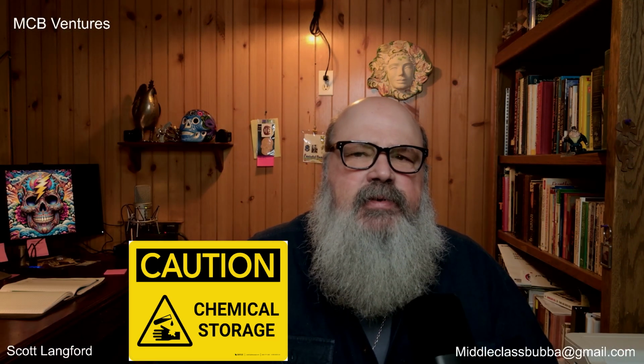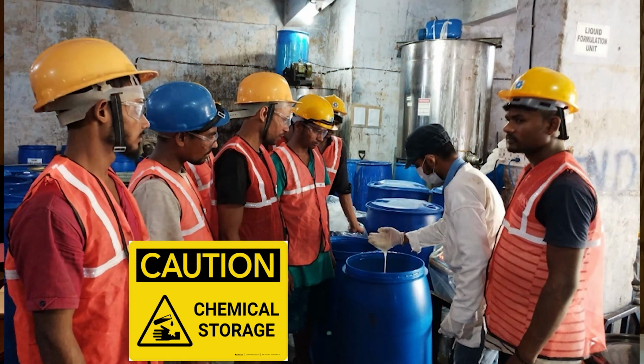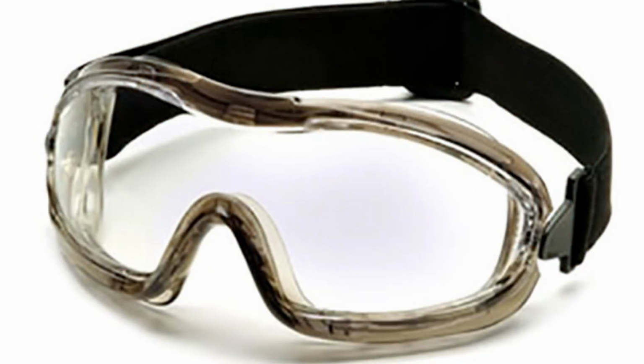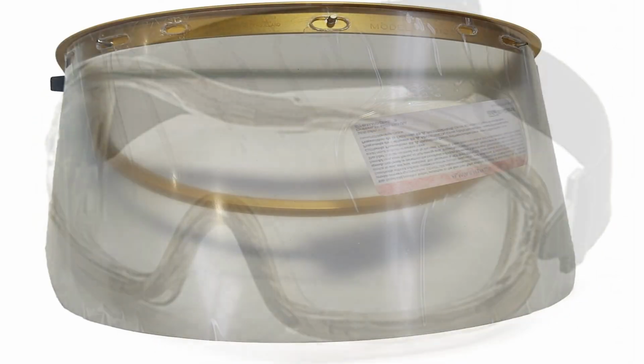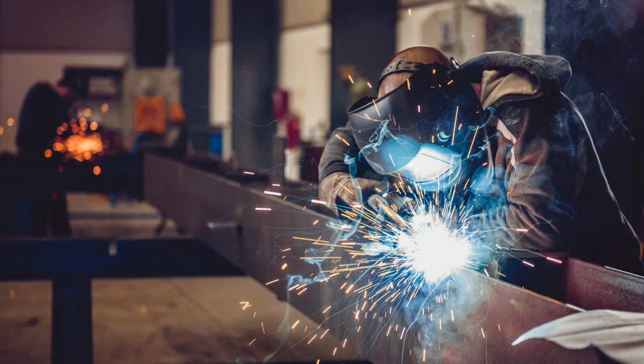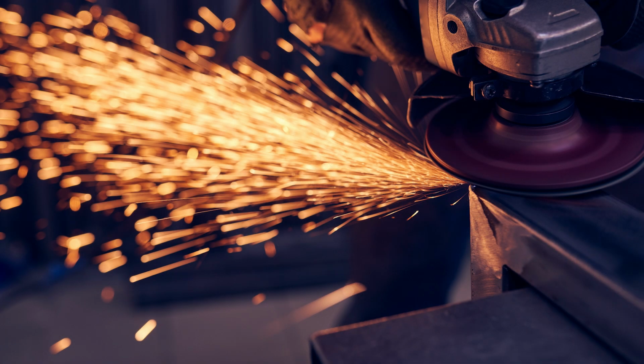Administrative controls. Post proper signage and train workers in safe handling of chemicals. Provide eye wash stations nearby. And finally, PPE. Use chemical-resistant safety goggles or face shields when working with chemicals. Next, let's talk about UV and infrared radiation. And that would be from welding, cutting, or some grinding operation.